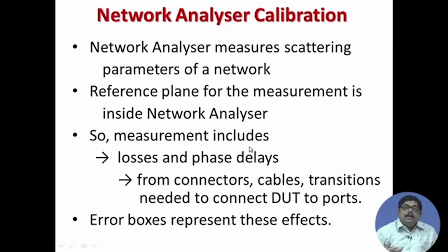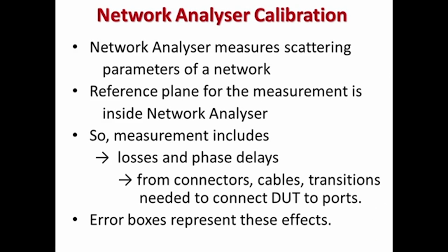Now, as network analyzer is a very precise measurement, these errors become significant. In microwave bench, etc., the measurement itself is not so precise. That is why even these errors caused by the change in reference plane do not come into such prominence, but here in network analyzer, since it is a very precise instrumentation, this needs to be corrected.